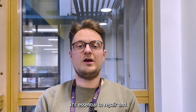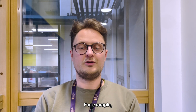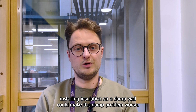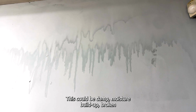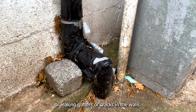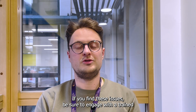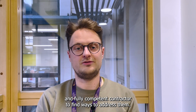It's essential to repair and fix any maintenance issues before you install any measures. For example, installing insulation on a damp wall could make the damp problem worse. So look out for key areas of disrepair. This could be damp, moisture buildup, broken or leaking gutters, or cracks in the walls. If you find these issues, be sure to engage with a trained and fully competent contractor to find ways to address them.